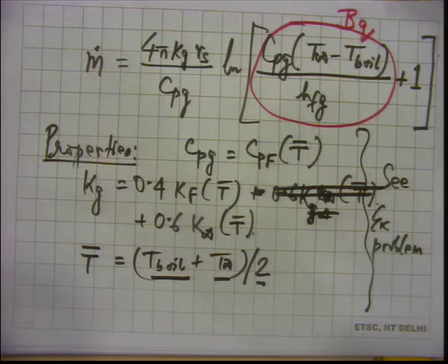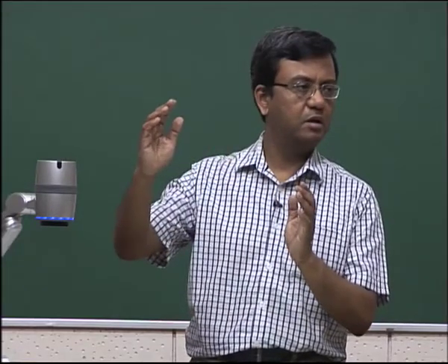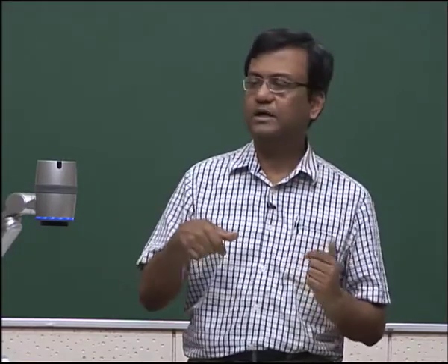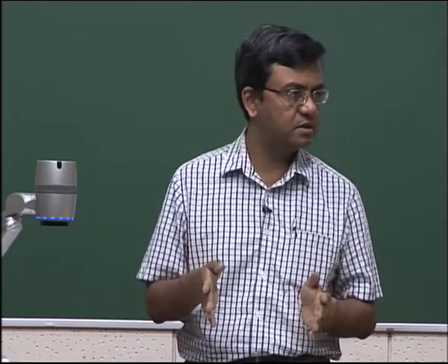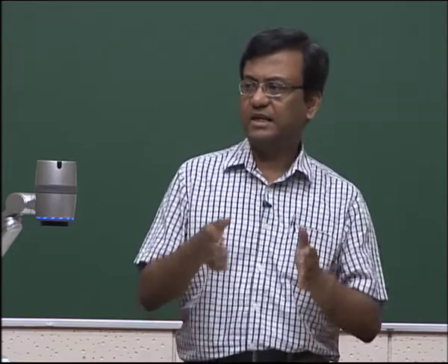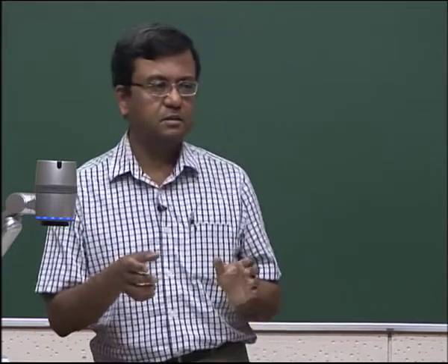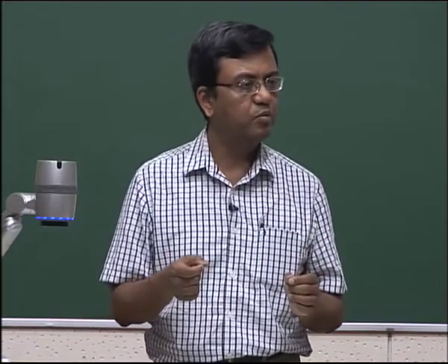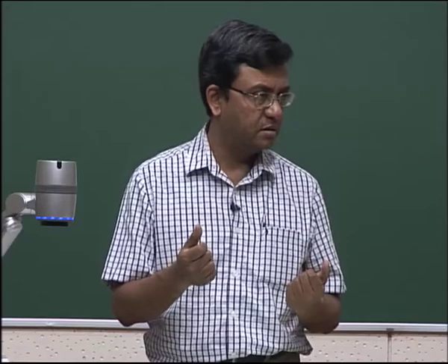Once you get m dot, so you have this droplet and there is this m dot, the mass flow rate around the droplet. We saw that that is constant within the constraints of our assumption, and we said that m dot is equal to m dot f. So, if we find m dot, then we have found m dot f, which is the fuel mass flow rate.